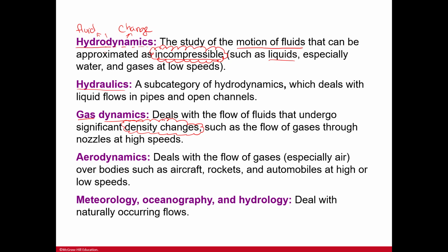And when we talk about gas dynamics, we are going to talk about density changes. And the reason why is because most liquids are incompressible. So that's why we have it as hydrodynamics. And gases are where you are going to find that density change when we're talking about a fluid. And so that's why we call it gas dynamics.